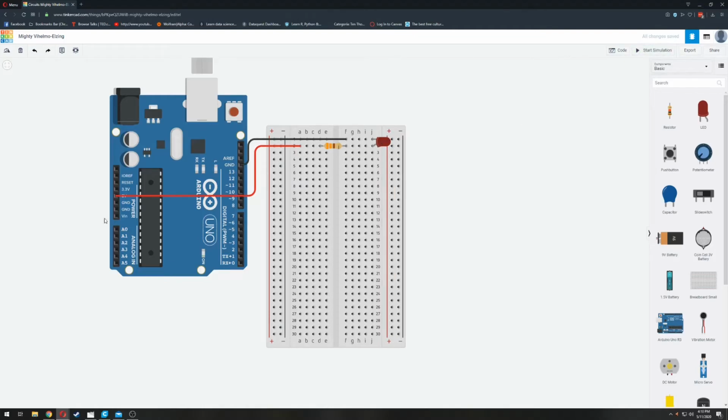The LED turns off. Let's go ahead and take advantage of that Blink script that's already here and see if we can make it blink. So this is much like your first Tinkercad example. This light is connected to pin 13. So I'm going to run it up from here. So instead of the 5-volt, I'm just going to pin 13. And I am going to use a yellow line for this, just to demonstrate something. I like yellow for signal. It just works best for me and how I think. So we'll click Run Simulation.